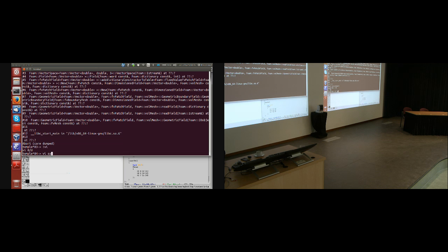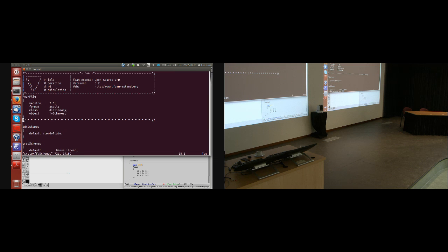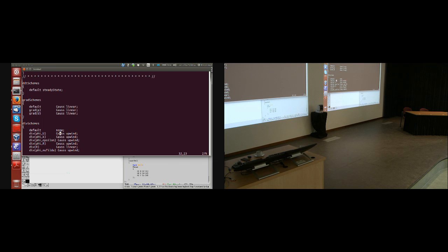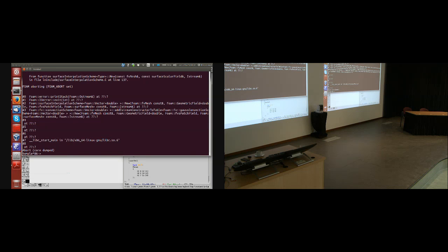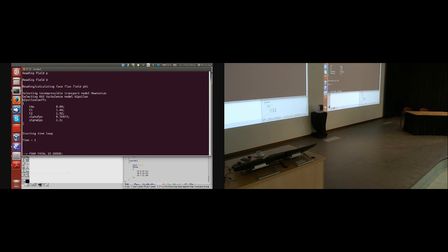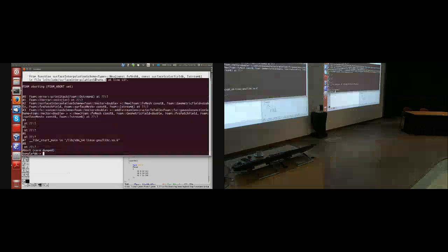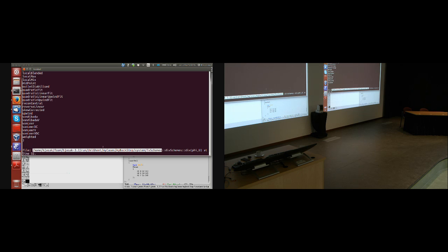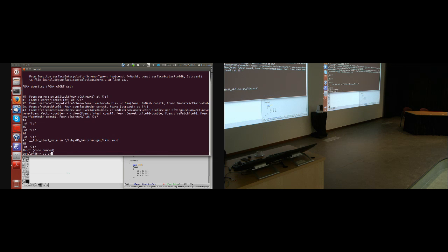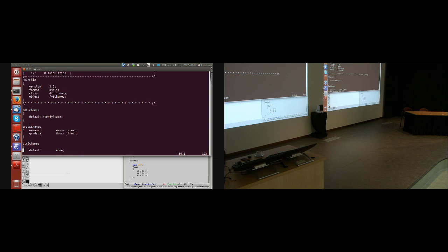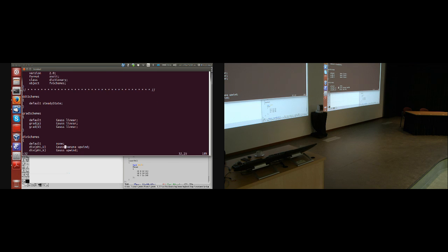Okay, now let's do something more complicated. fvSchemes, default scheme. Now it says FOAM fatal IO error, unknown discretization scheme banana, valid options are blah blah blah, in file system/fvSchemes, diffusion scheme, div(U) at line 32. Okay? Line 32, and here's my banana.